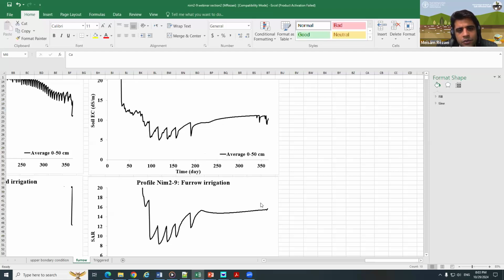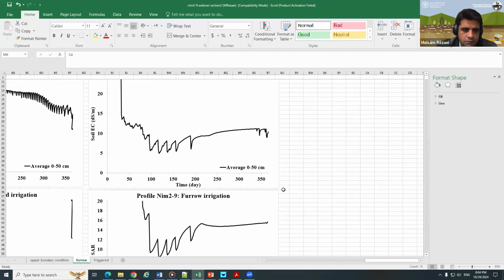That's why farmers try to have a pre-irrigation before cultivation, to reduce the effect of salinity on the emergence of the crop. So that's it for scenario 1, which means we had furrow irrigation based on the definition of the problem. So we say, okay, we have this amount of water. We want to shift from furrow to a different irrigation system like drip irrigation, or even a strategy to give the field water every 2-3 days, to reduce the salt stress as well as the water stress.